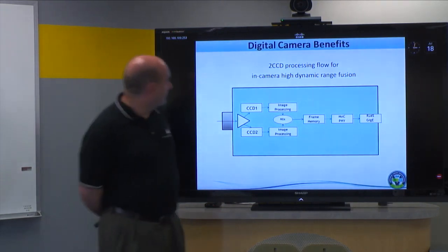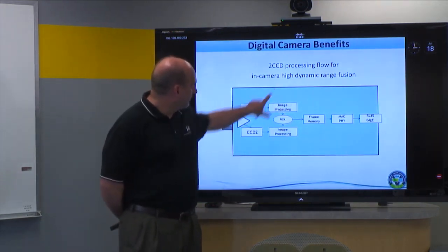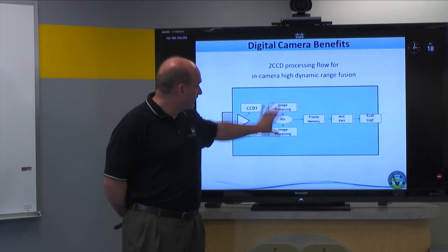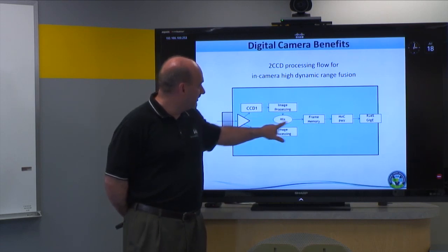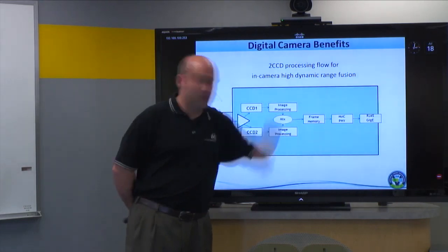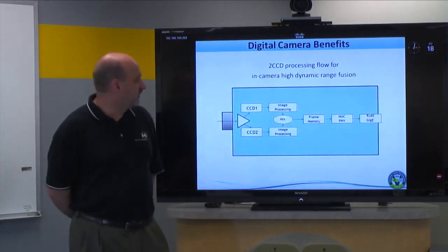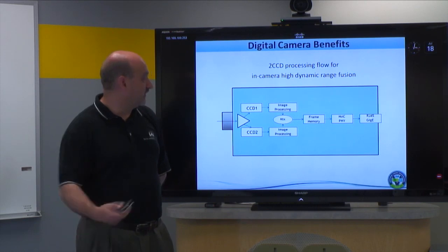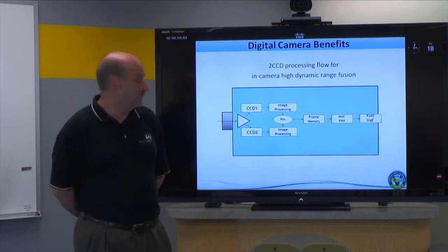So this, again, is made possible because we have a smart processor in the middle, and I can do image processing and actual fusion, feed it through a memory circuit, and now the rest of this would be typical output for the camera: a physical interface and a format, in this case, gigabit Ethernet for vision.